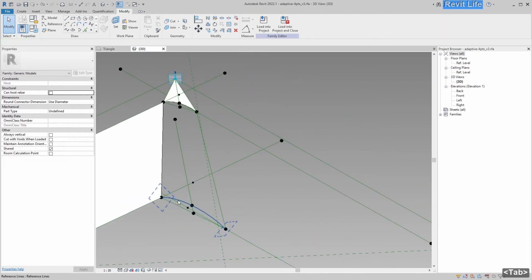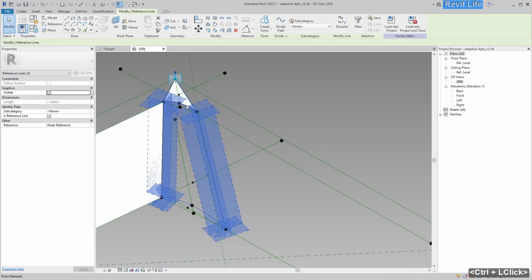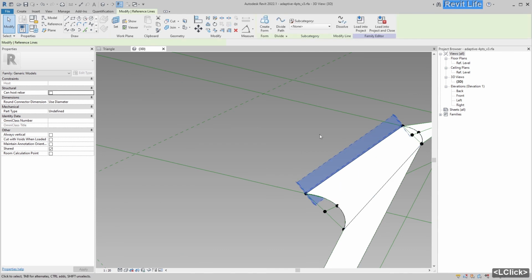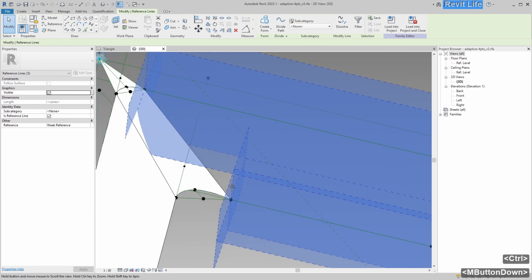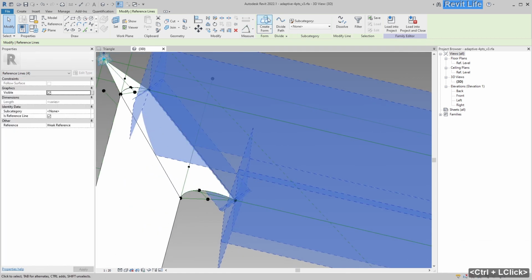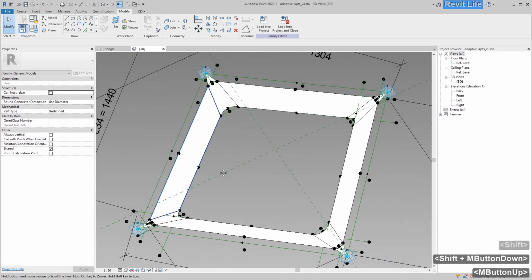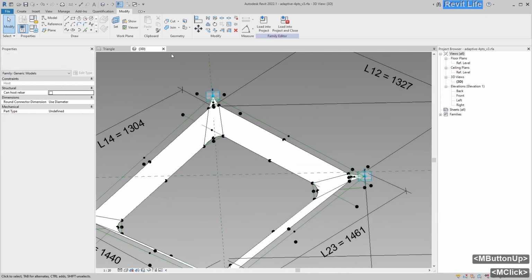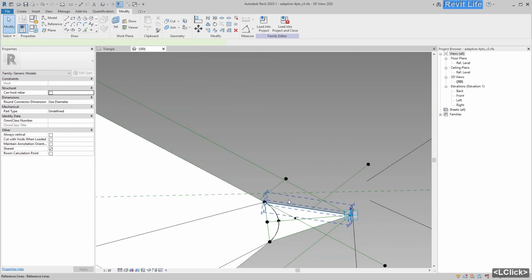This one, select four borders, 2, 3, 4, create form. And let's move on to the next one. Select four borders and create form. Okay, select surface. And if you don't succeed, just select those reference lines in different order and try again, because this is some kind of bug, and you just have to select it a few times just to see the menu.